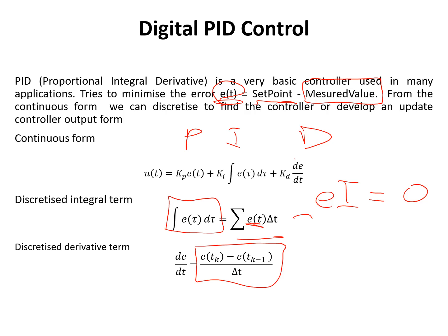We take the previous error term and store it, subtract that from the current error, and we have the difference in errors. And then we divide it by delta t. And again, this delta t is the time between the controller steps. So this controller would run at, say, 1000 Hertz. If we're sampling our analog data perhaps at 1000 Hertz, our controller might run at the same frequency. Or you might want to sample your analog data much faster, say 10 or 100 kilohertz, and then do some averaging, some filtering using that data, and then run your controller only at 1000 Hertz.